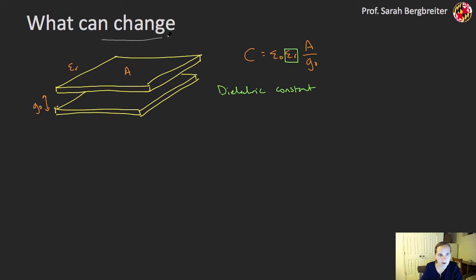Another fairly popular configuration would be to actually have this top plate suspended in some kind of mass spring damper system. And this is very common in the inertial sensors that you also have on things like your phone or a quadrotor, for example. And in this case, as I am accelerating, for example, maybe this is a larger mass, the position of this plate is going to change relative to this plate.